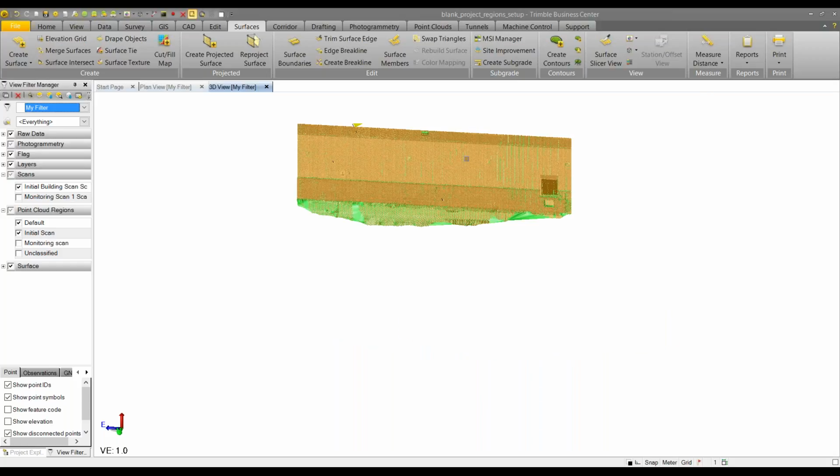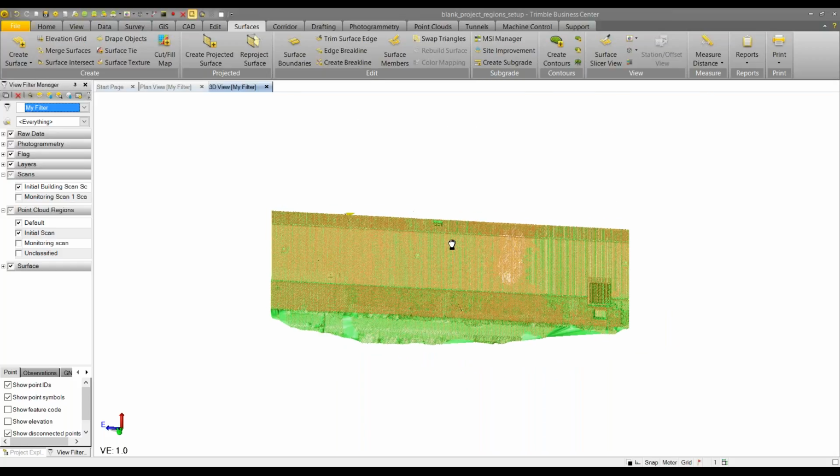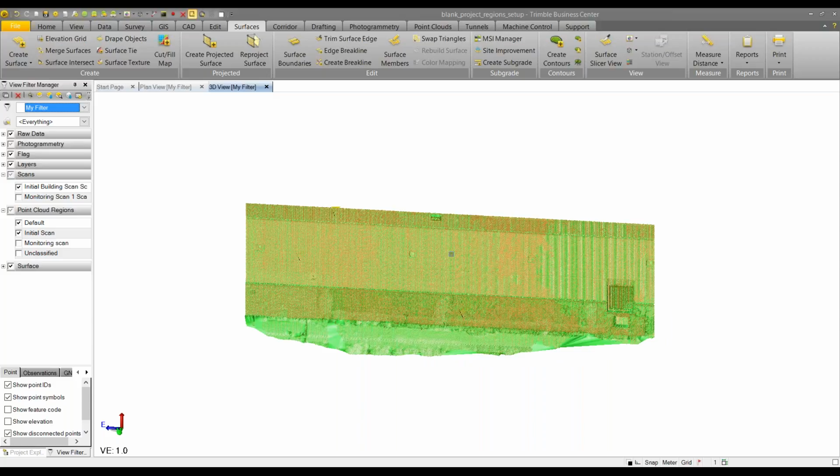There we go. Got a question from Harry: what effect does locking your plane have in the plane definition manager? So locking your plane means that it can't be changed. You can't mess up the plane at all. You can't redefine it. It's just a toggle to prevent that, and it can be unchecked or checked at any time. So it's just a means to keep it from being modified.